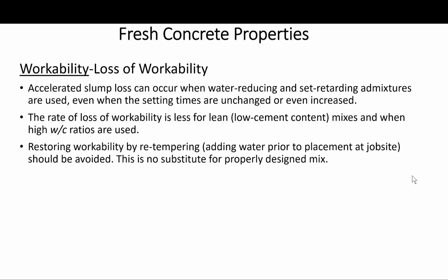This is a general statement, and I'm mentioning it just for the sake of completeness of the presentation. I do not by any means condone or encourage this practice, which is adding water to the mix at the job site. This should be avoided at all costs.